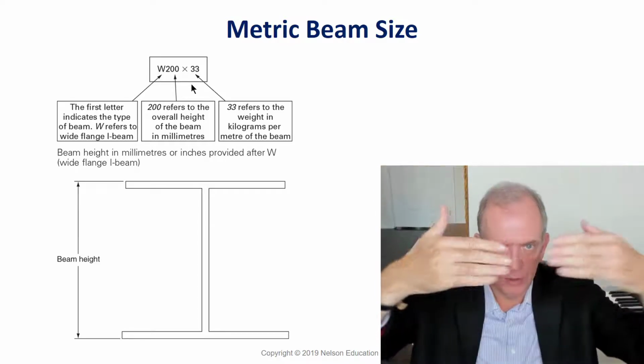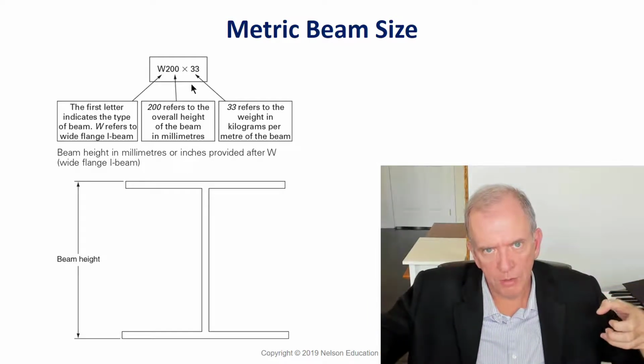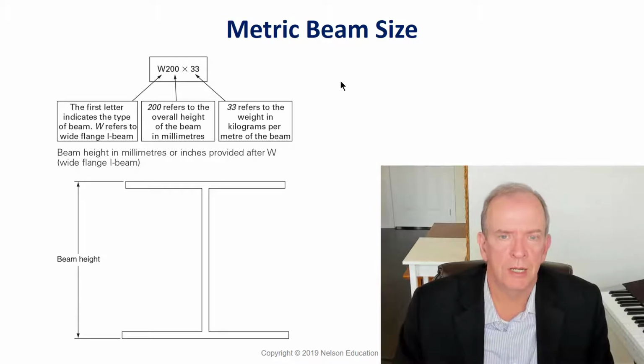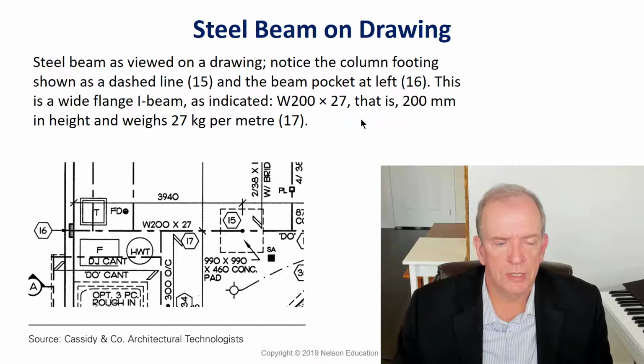So it's got to be carrying the supported length of the joists, what's the span between the columns, and how many floors is it supporting when we're talking about beam design. And there's a bunch of predefined tables in the building code that can be looked at that give you those dimensions and sizes pretty easily to tell you what standard beam size you could use.